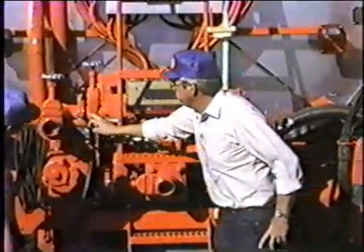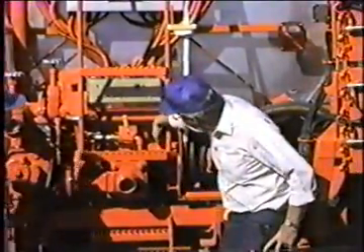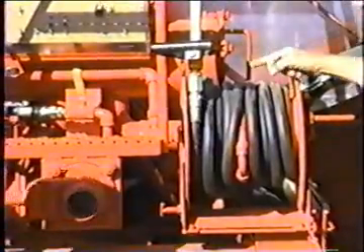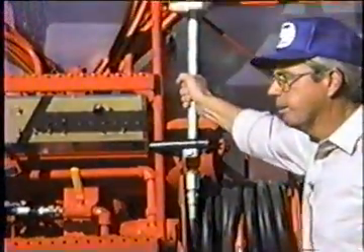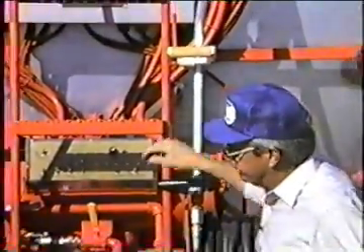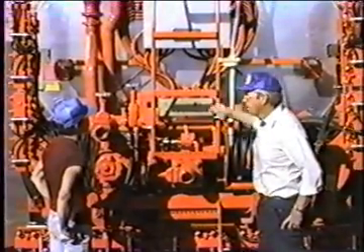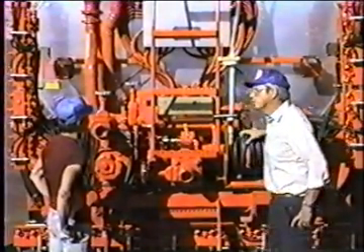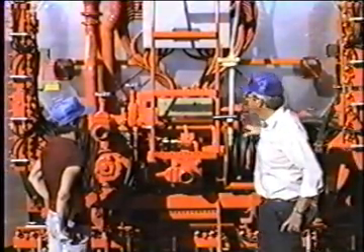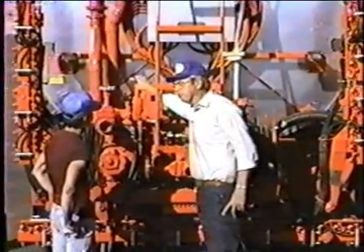If you trace this from the valve, across this pipe it goes into a swivel that goes into the hose reel here, and comes out of the hose reel through 50 feet of hose into the handle here. Path of least resistance: it's a lot easier to go through all the 2-inch and 3-inch piping in the spray bar back to the tank than it is to come out this 50 feet of hose. So you're not going to get anything if you just do what we've done so far. You've got to stop the flow from going to the spray bar, so close the spray bar valve right here.